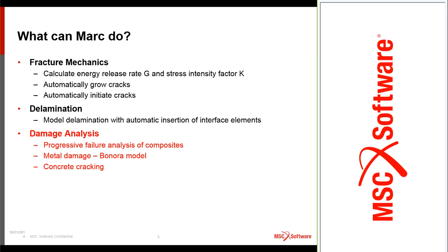In the area of fracture mechanics, what we can do with Marc today is to calculate energy release rates, G, and stress intensity factors, K. Basic quantities for fracture mechanics. We can grow cracks automatically, and we can initiate cracks automatically.